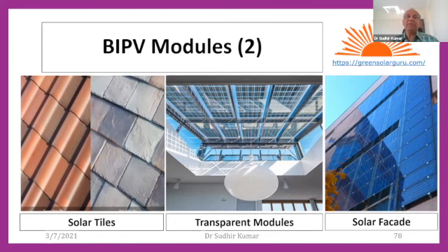All cells. So that means you have to make sure that all of them should be 300 watt. And at the most, you can have plus minus 0.5%, not more than that. Yeah, I mean, in respect of wattage. 0.5% variability.